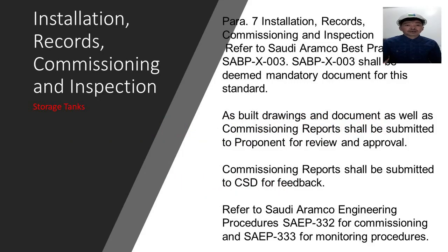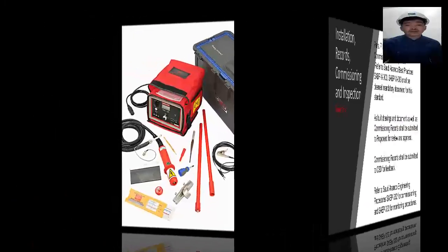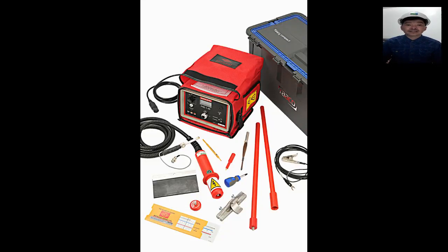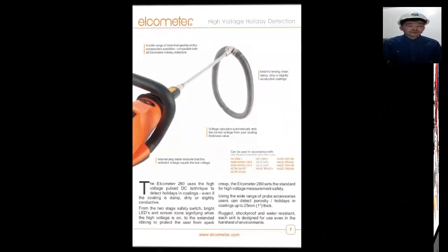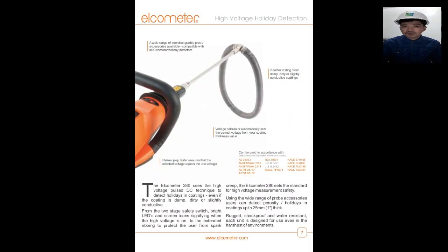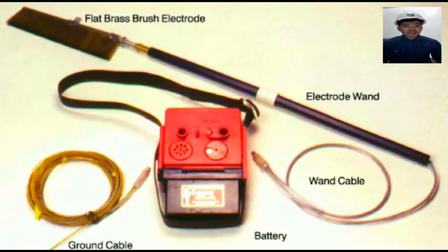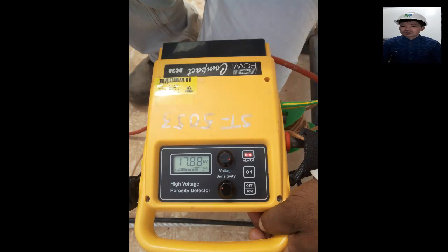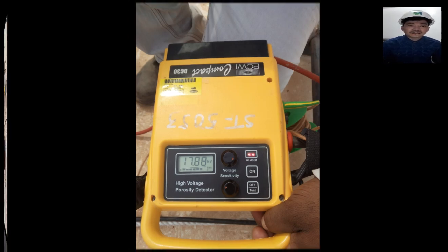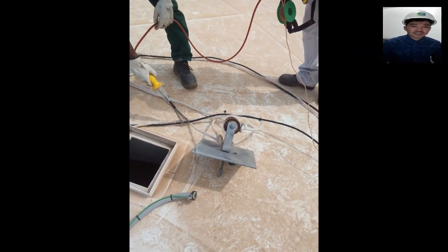By the way, for the cable testing, we are testing the positive cable or the CP cable with 18,000 volts. We are doing the holiday test using impulse holiday test detector. I forgot to tell you the test, but I just remembered it. It is very important, and especially the positive cable, we are not allowed to repair it. Maybe by accident, it's a matter of approval. We cannot do any repair. Actually, we are not accepting any defect or repair.